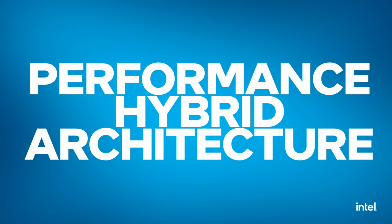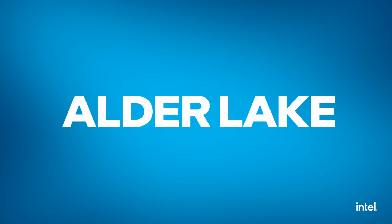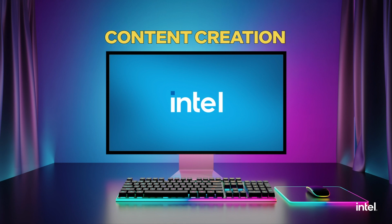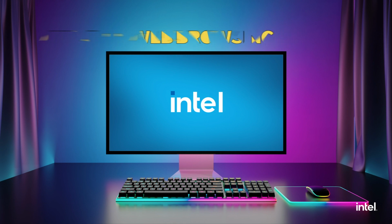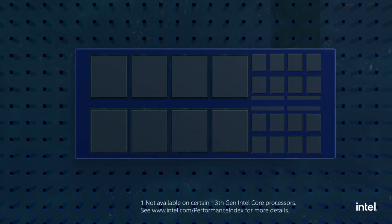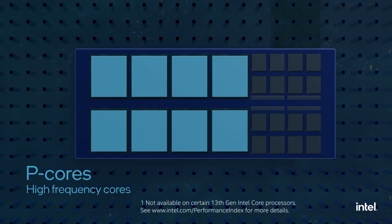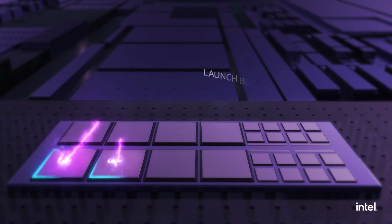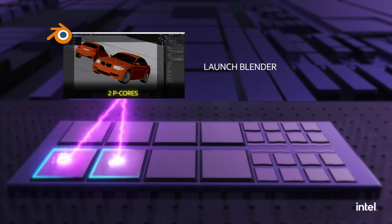So how does Thread Director work with performance hybrid architecture? That takes me to Alder Lake, Intel's 12th generation processor and the first of its processors to use Thread Director. Intel saw the need for a system that could tailor its performance to the requirements of any workload. Not every workload requires high-frequency computing, and approaching computing that way is not the most effective use of your processor. To do this, Intel created their first hybrid architecture processor. These processors have high-frequency P cores for high-performance tasks, as well as lower-frequency E cores meant for modern multitasking. This hardware presents a platform that can have the best core available for any type of workload.